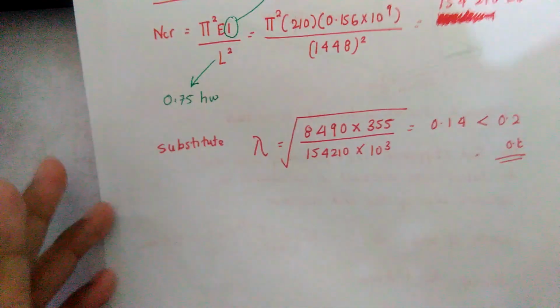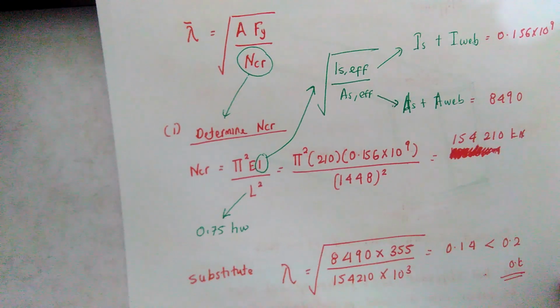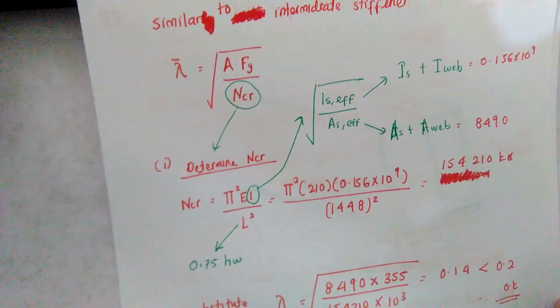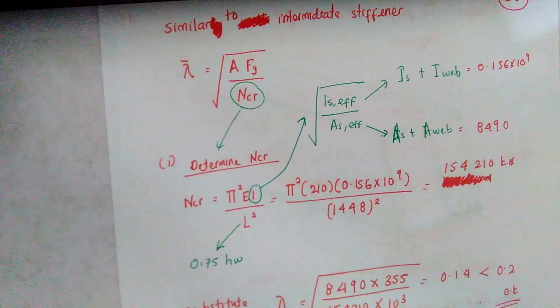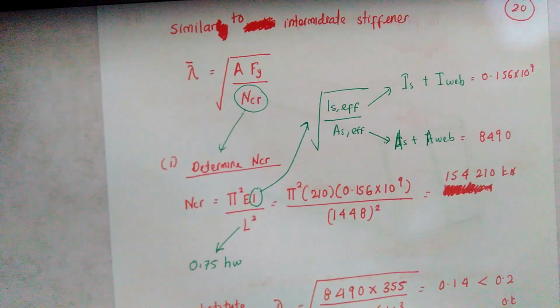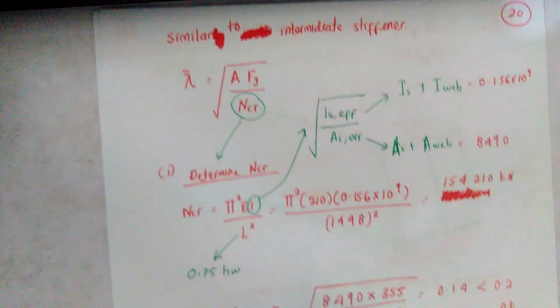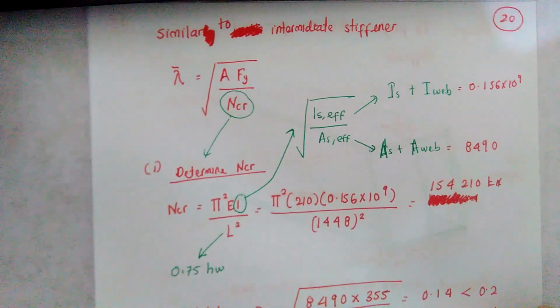So in this particular case, we repeat the same process whereby we now need to check whether the stiffener that we propose at the end of the plate girder, with the size of 500 mm times 15 mm, is satisfied or not, or whether or not we need to conduct the shear buckling resistance check.